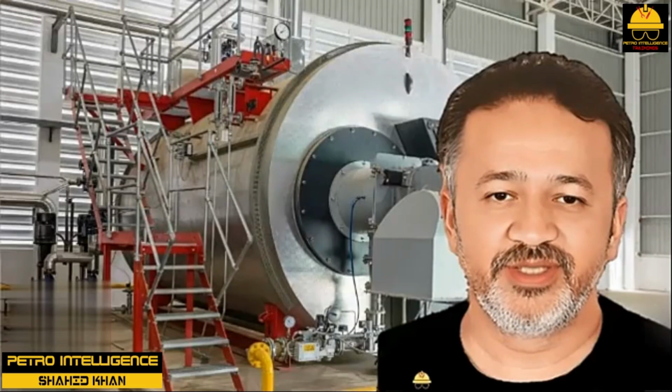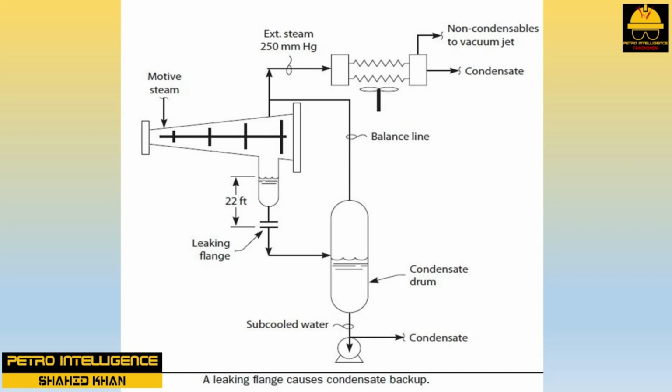Air-cooled surface condensers. This picture shows a surface condenser elevated above the steam turbine. This creates an additional problem in that moisture from the turbine exhaust steam will accumulate in the bottom of the turbine case. A special drain line from the turbine's case is needed to prevent condensate backup from damaging the spinning wheels. One such turbine in a refinery would not drain properly.